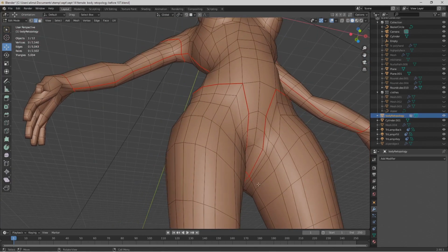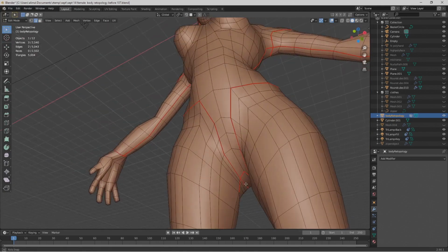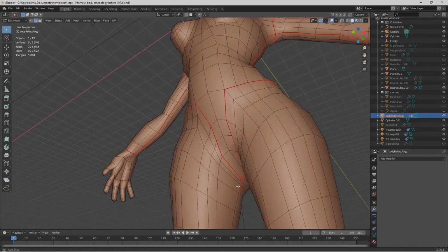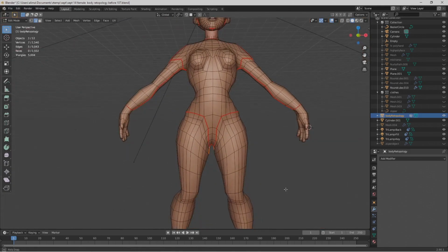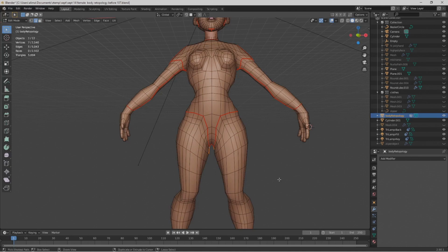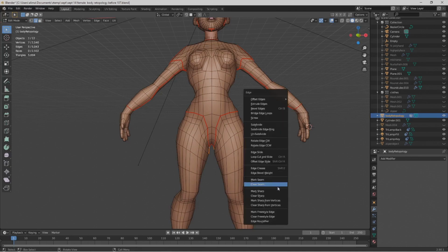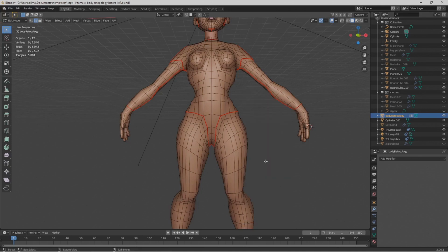So here, I'll select here. The manipulator's in the way, so I'm going to the upper left. I'm going to hold Shift, select here. Hold Shift, I'm trying to see. Select here as well as here, as well as here. Zoom back, and then just like we put the seams there, we can hold Control, press E, and then we can select Clear Seam. So now those seams are gone.